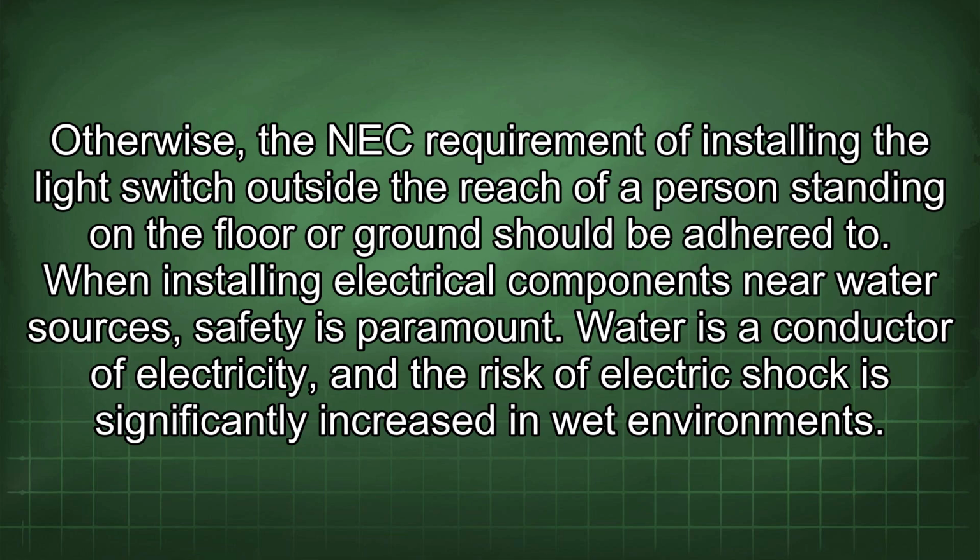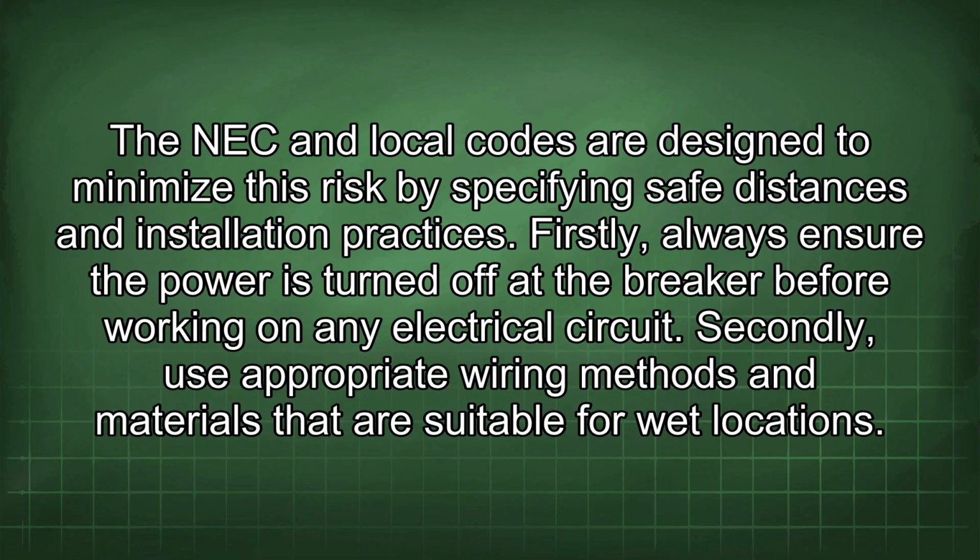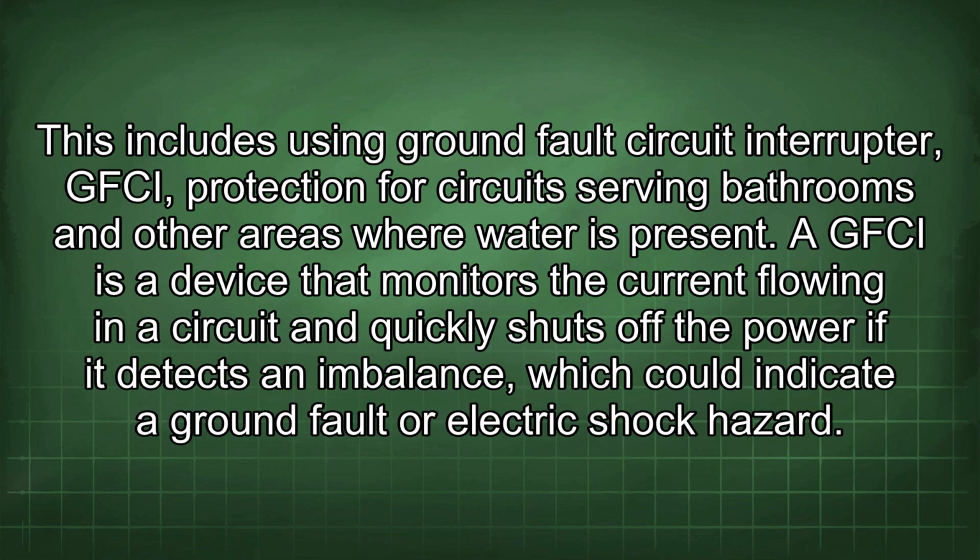When installing electrical components near water sources, safety is paramount. Water is a conductor of electricity, and the risk of electric shock is significantly increased in wet environments. The NEC and local codes are designed to minimize this risk by specifying safe distances and installation practices. Firstly, always ensure the power is turned off at the breaker before working on any electrical circuit. Secondly, use appropriate wiring methods and materials that are suitable for wet locations. This includes using ground fault circuit interrupter, GFCI, protection for circuits serving bathrooms and other areas where water is present.